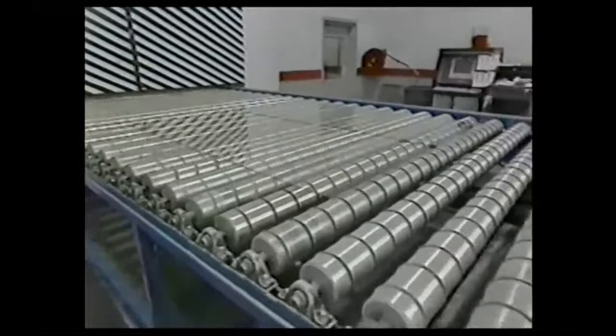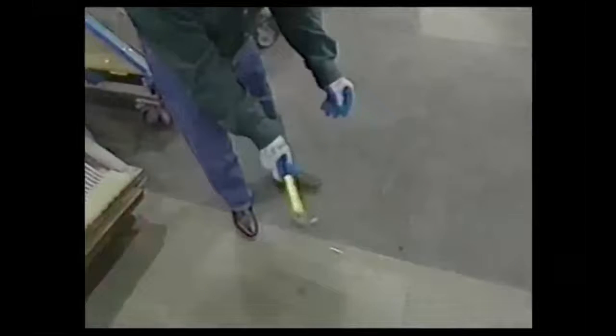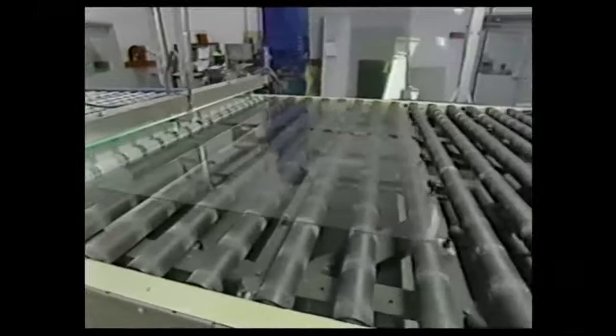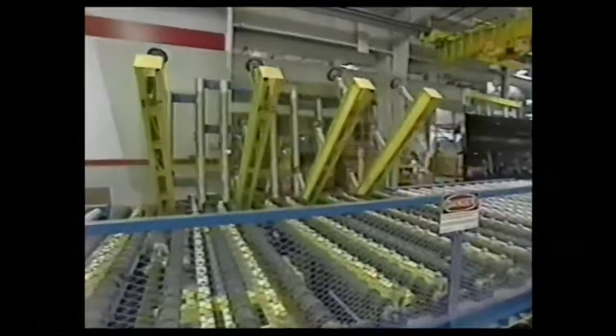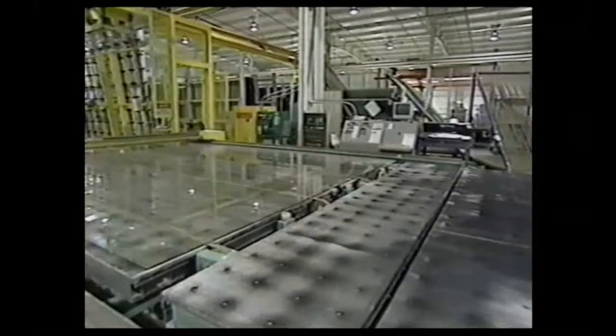After glass is tempered, it is up to 4 times stronger than annealed glass of the same thickness when exposed to uniform static pressure loads. If broken, the entire piece will fracture into many cube-like pieces, which are less likely to cause serious injury to people. Most architectural glass can be tempered. Once annealed glass has been fully tempered, it is not possible to alter the appearance of the piece. For instance, holes, polished edges, and notches must all be completed before the glass is tempered. If any additional processing is attempted after tempering, the piece will shatter.